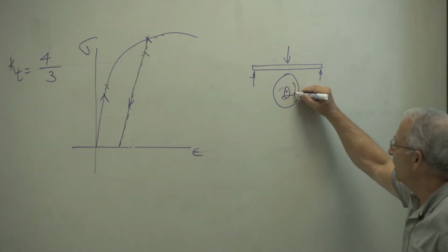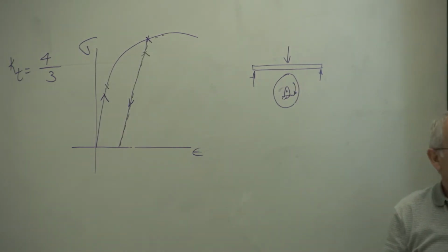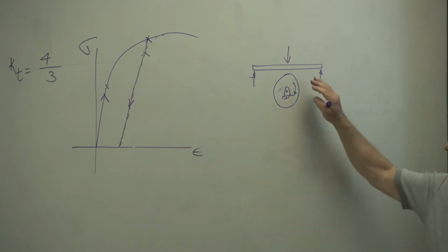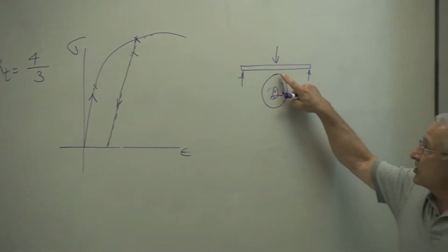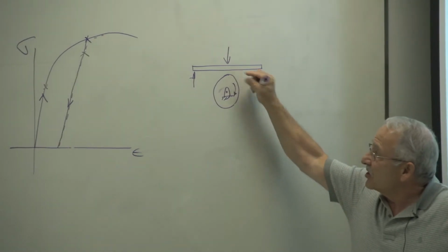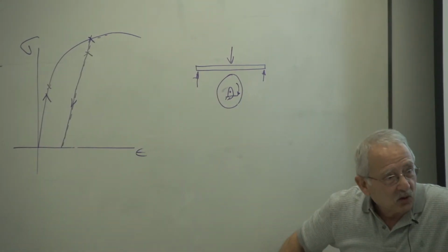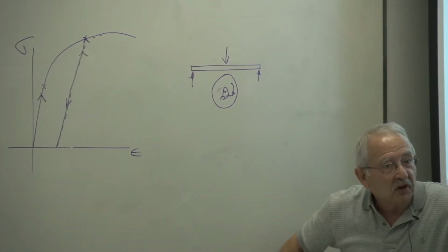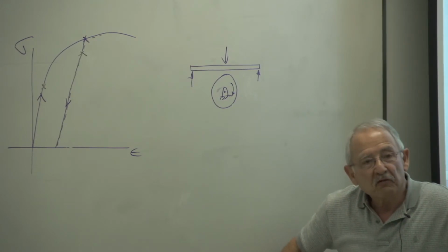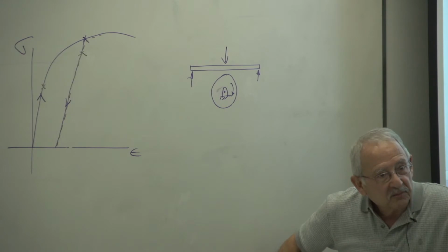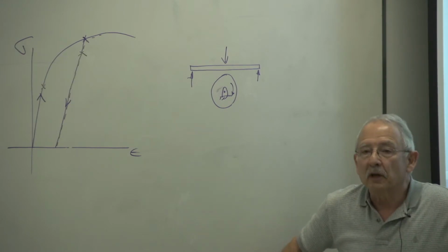This is a flywheel, needs to rotate. And then you have a beam sitting on top of it with a load on it. If the deflection at this point is larger than the gap that is there now, then the beam and the flywheel will touch, and the beam will interfere with the function of the flywheel. The beam will have failed.